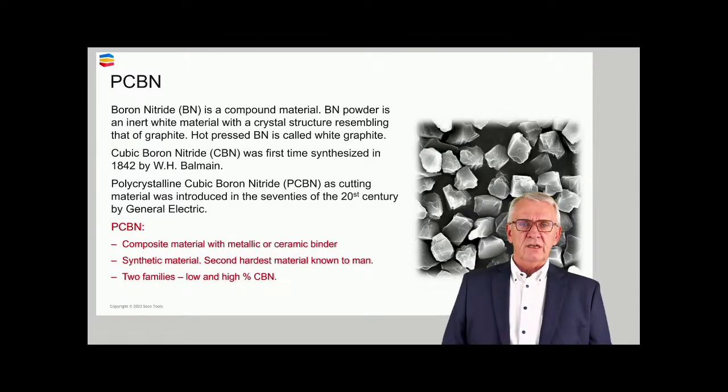So a composite material with a metallic or ceramic binder, that's what we talk about. It's synthetic. It's man-made. You don't find it in nature. And as far as we know, as a family of materials, it's the second hardest material we know after diamond. And if you look at these PCBN materials, and be careful, I make the same remark as I made last time,